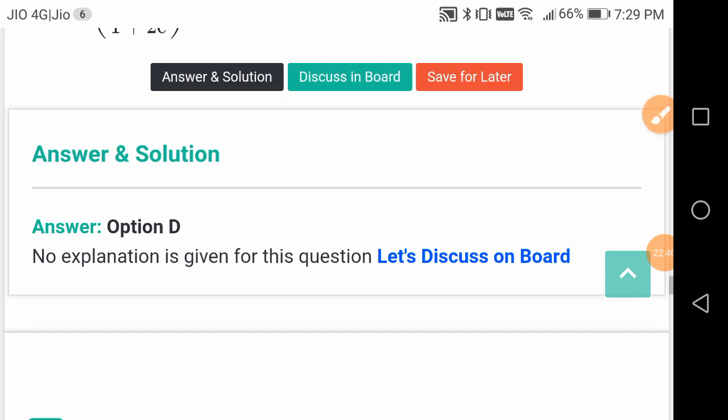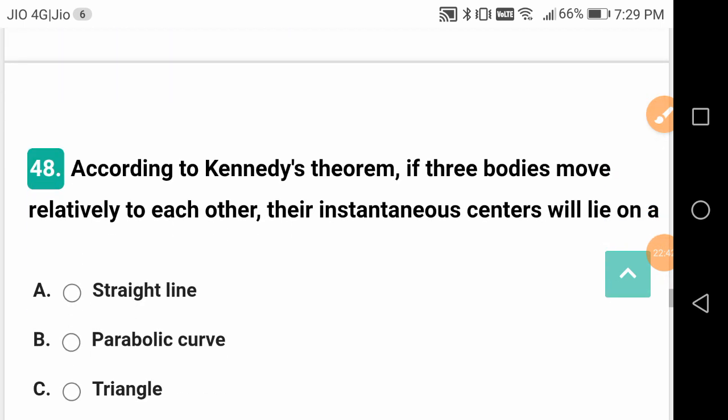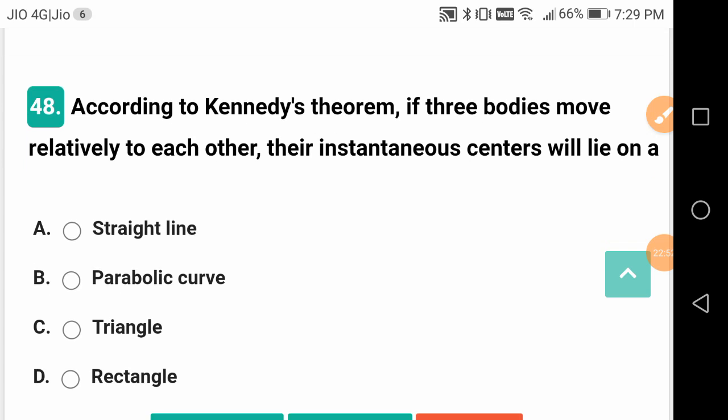Power of the governor. Power of the governor is energy. It has the units of energy, not watts. It shall be joules only. It's a misnomer. Normally we think that the power of the governor will be specified in watts, which are the units of power, but it is not so. It is simply energy. So the power of the governor should always be expressed in joules, which is the unit of energy or work.